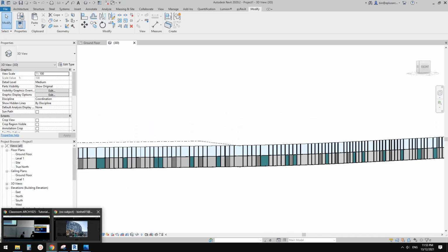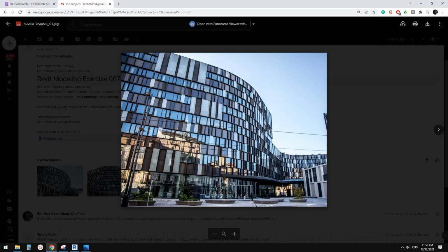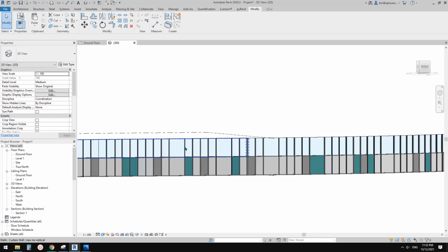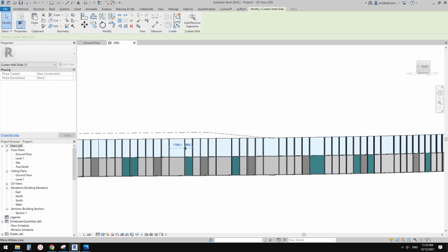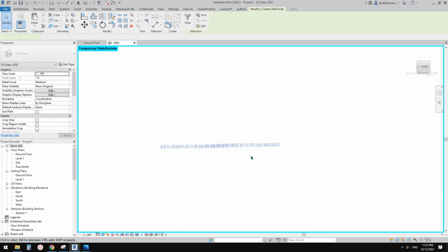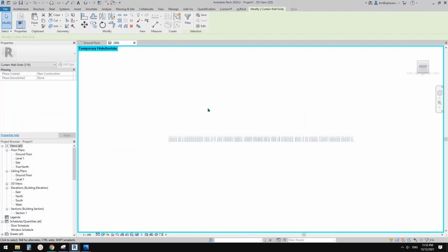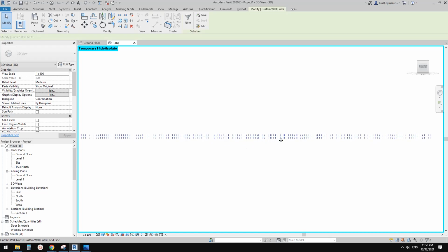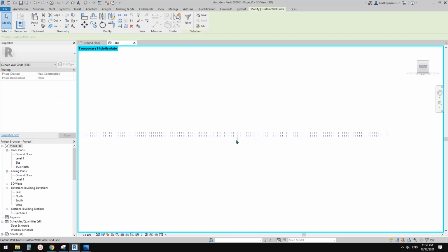And you might think actually it's not aligned. See, it's not aligned, but that's okay. So what we can do is we can tab select one of the grids, IC, and just roughly. So see, this is 2 levels, right? So let me click on the front. So now it's easier to only select the top one, so top grids. And what I'm going to do is I'll just move them to the left or to the right. Maybe to the left. Okay, I'll use shift left so it moves faster.